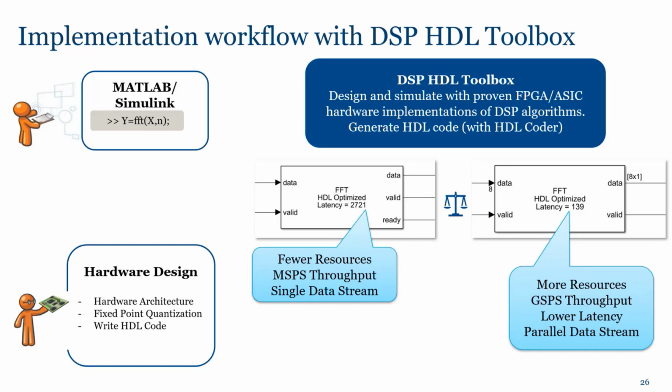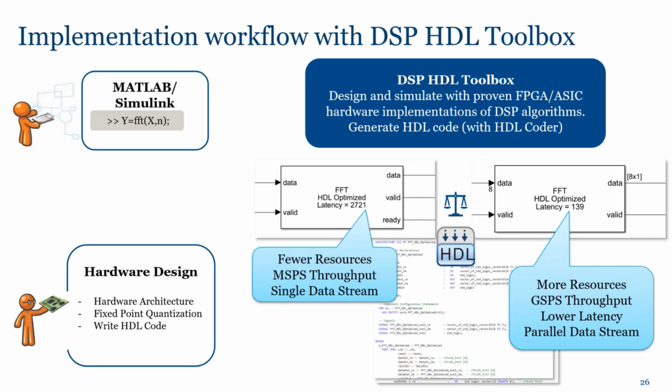So the idea behind the DSP HDL Toolbox is to be able to simulate the effect of our choice, our implementation, before even generating the code. So you will validate your choices in Simulink, in simulation. Later on, go through code generation, where you can also validate your choices in simulation, and we'll see how we can compare what we have in Simulink to what we have in generated code.